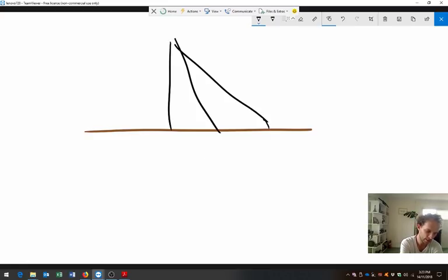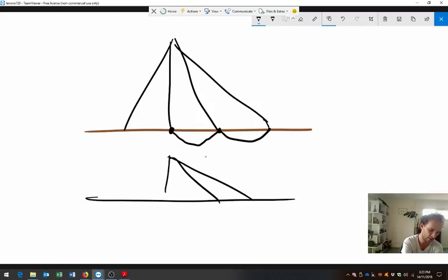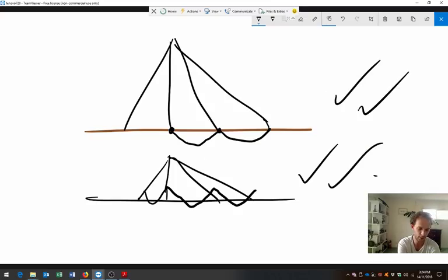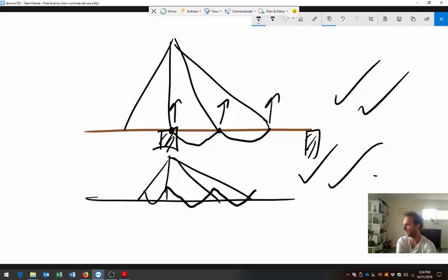continuous. If it's simply supported, our bending moment diagram is just going to look like this between the cables. If it is continuous, let's draw another one maybe. If it's continuous, then our bending moment diagram is going to be negative at the cables and positive in between, like this. Both answers this year got full marks. But yeah, I guess the point of this question was to understand that it's these cables that are providing the support to the bridge. It's not the actual piers of the bridge, it's the cables. That's what needs to be understood.